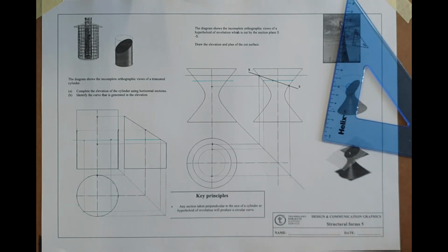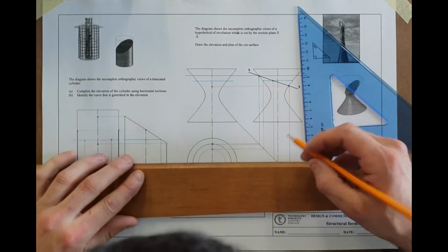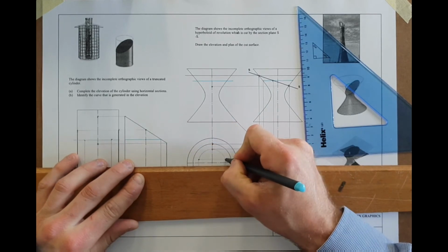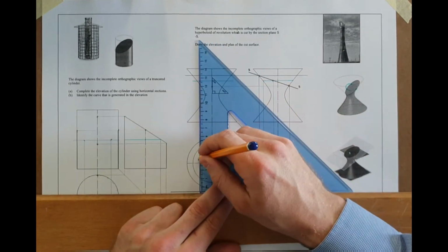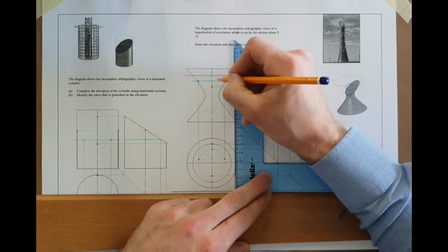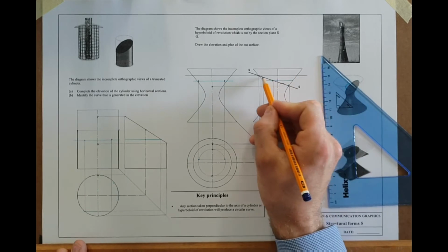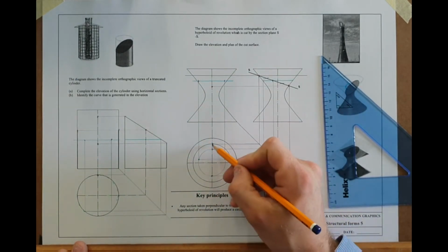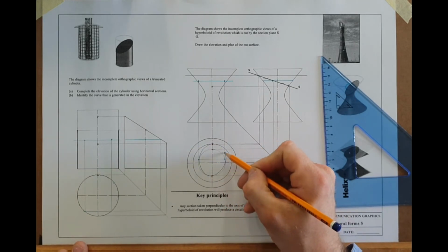And the points on that horizontal cut are there. I have them in plan. I can get them in elevation. And if you keep repeating that, and let's say you drop in one more here and one more here possibly, and show your cuts and plans, show them in elevation, you will end up getting a freehand curve that goes from the top down to the bottom and back up.